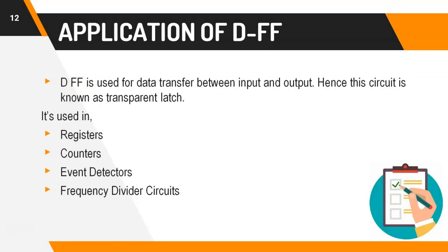Coming to applications, to transfer the data from input to output, we can use D flip-flop since this is a transparent latch. Other than data communication, it can be used in registers, counters, event detectors, and frequency divider circuits, etc.